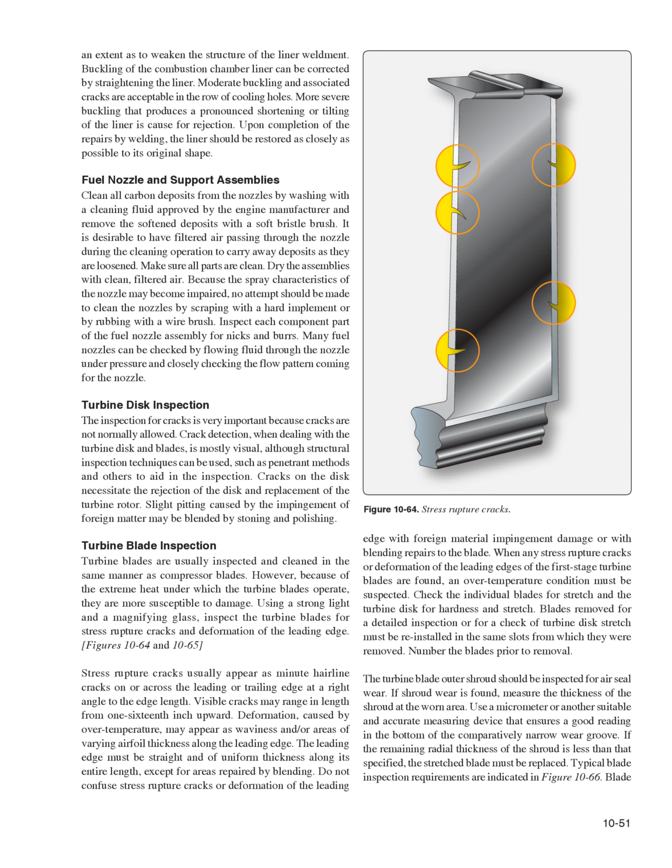Check the individual blades for stretch and the turbine disc for hardness and stretch. Blades removed for a detailed inspection or for a check of turbine disc stretch must be reinstalled in the same slots from which they were removed. Number the blades prior to removal.